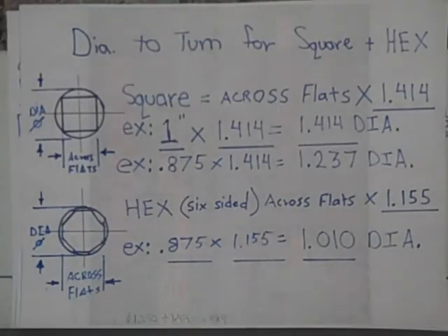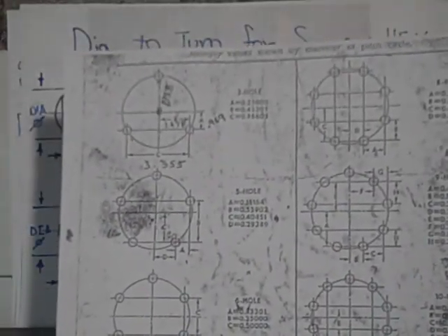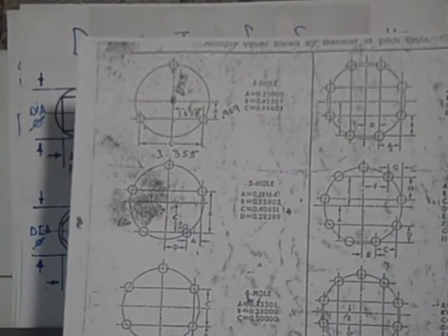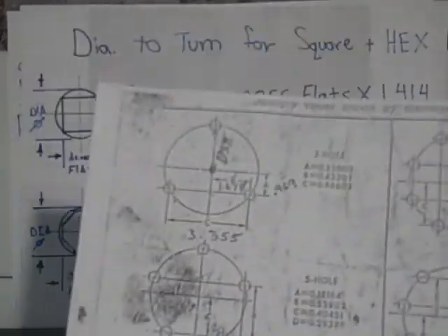This one I don't use often, mostly at home whenever I use it, and bolt circles I haven't used in years. This works best with a set of digitals on your milling machine, and some of the digitals actually have calculating bolt circles on them, but you don't even need this anymore. I'm still going to tinker around and try to figure out a way to get this on there so I can show you. It's really helpful.